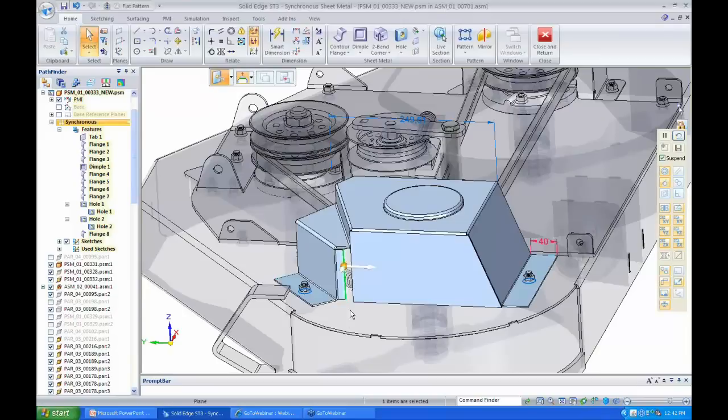So how to get that gap? What I can do is just click the Shift key on my keyboard and then click on the primary axis. So in this case, my gap is going to be 1 millimeter. So I'll just enter 1 millimeter and then place it, and then I can click on the primary axis and select this edge that is on the bottom left corner.